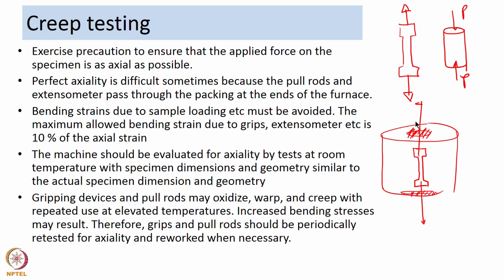So, if such a case is there, then the bending strains due to the sample loading etc., have to be avoided, and even if it is unavoidable, then the maximum bending strain due to grips, extensometer etc., should be maximum allowed bending strain is 10% of the axial strain.